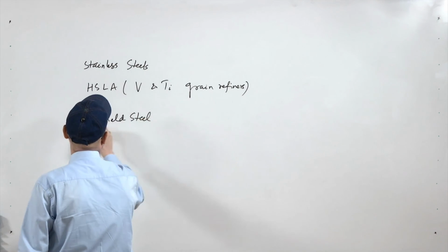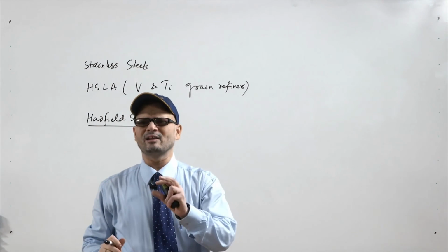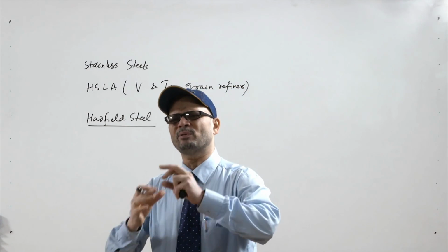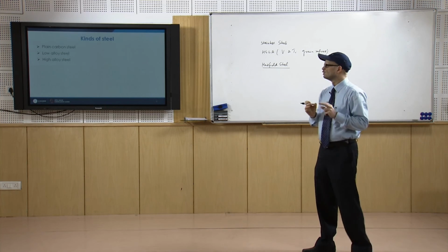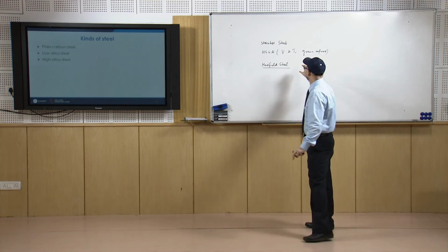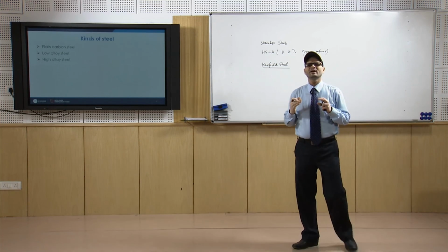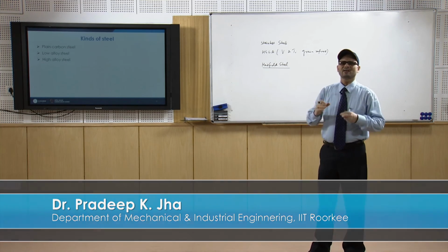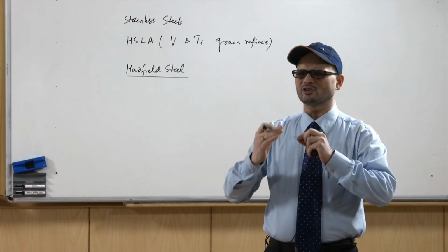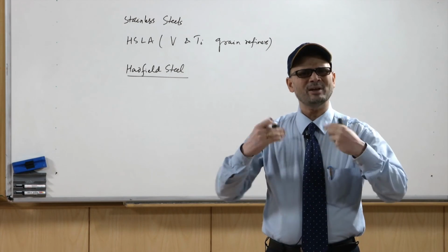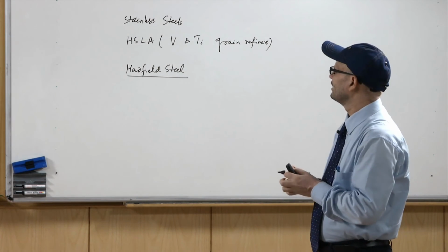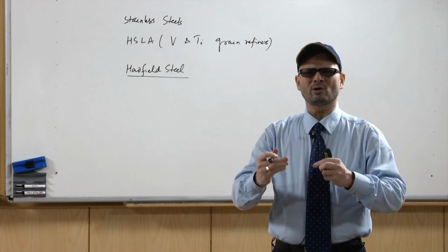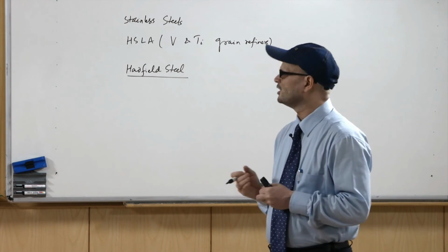That is austenitic manganese steel, where you have manganese at a higher level, and that gives a large amount of wear resistance. So, depending upon the type of alloying elements, you will have specific properties in different kinds of steels, and the process of producing may vary slightly because the treatment may vary, the refinement may vary. This way you may study more and more about the different varieties of steel and get to know about their uses and their melting processes.